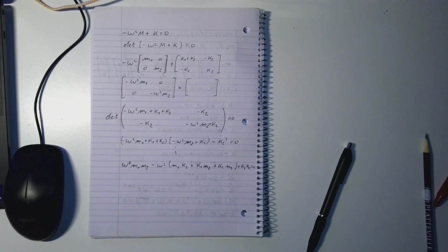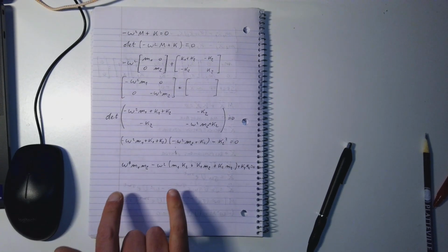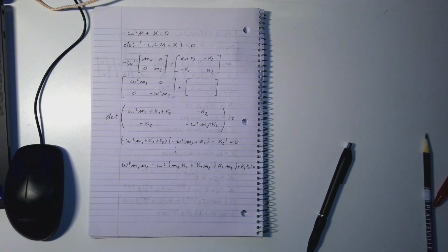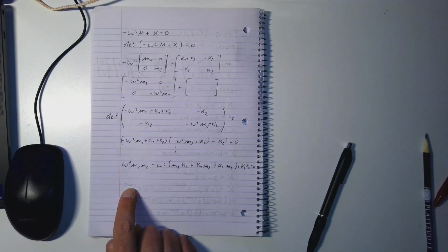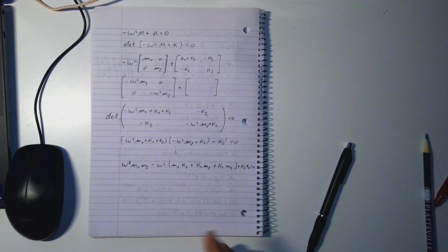One will be plus or minus a certain number, the other one will be plus or minus the other number, pretty much. So when we look at this, of course we are not going to consider the negative value of the frequency, because physically we are going to look only at the positive value of the natural frequency. So out of those 4 solutions, 2 positive and 2 negative, we are going to look only at the positive solutions. Make sense? So that's why eventually we end up with only 2 natural frequencies.